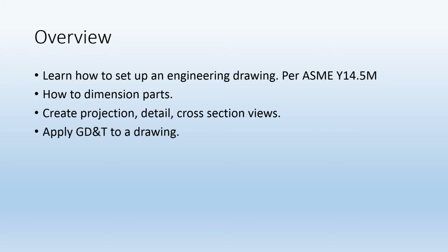So if you've ever taken a class on machine design, they go through this a little bit. You can apply plus minus dimensioning on there. So you can imagine that if it's a very precise part, and of course here in the United States we're using English units, so inches, we could say that we'd like to dimension from either wall, so 1.5 plus minus 5/1000ths of an inch. So that would be 1.5 plus or minus 0.005 inches. You could move 0.005 to the left or to the right, and then up or down from the point, and you'd still technically be within your tolerance.